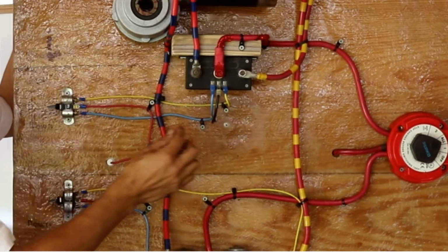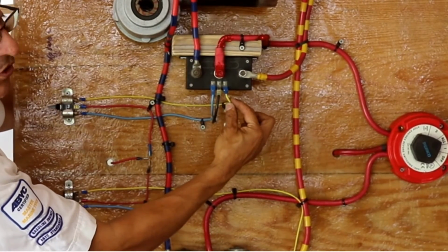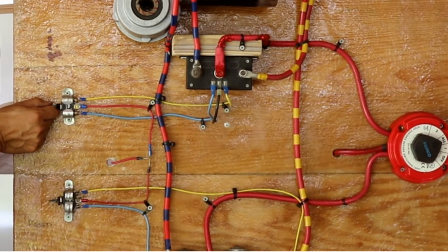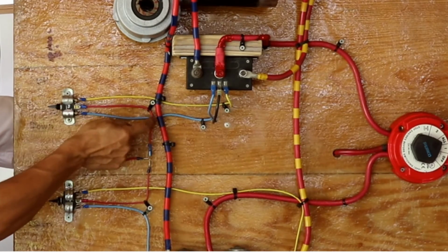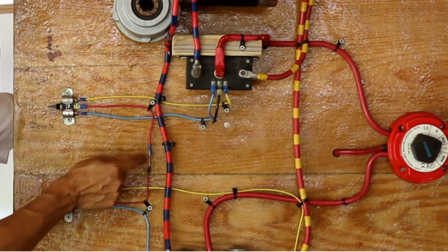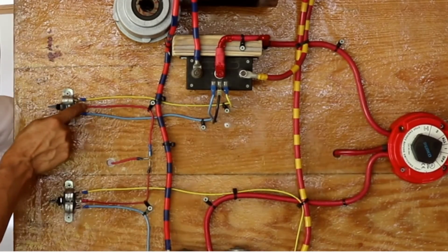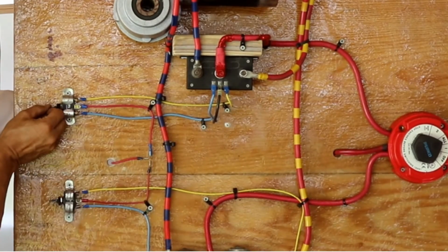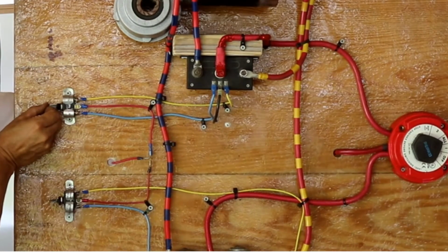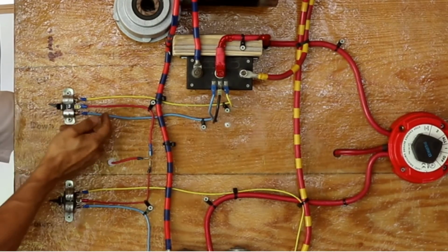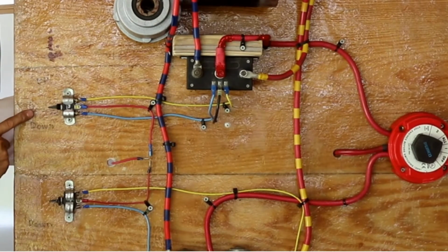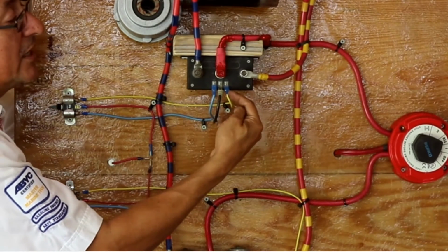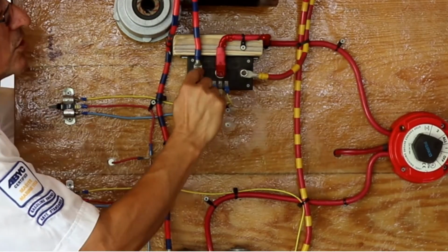position. Okay, the signals for clockwise or counterclockwise are coming from this single toggle switch. The input is in the middle. The input, the positive, is coming from the battery, enters in the middle, and I have one possibility: rotate clockwise or rotate counterclockwise. The only thing I need is to bring the signal here or bring the signal here in order to send the power over there or send the power over there.